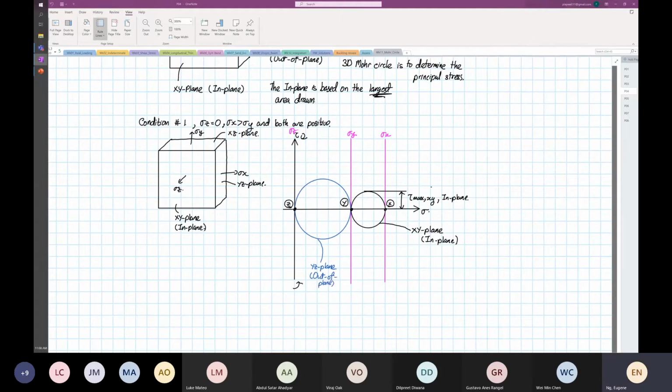And what you realize is now the diameter goes bigger. Okay. And then where do you have that? Over here now, which I'm drawing now. This is your shear max in your YZ plane. Okay. And it's out of plane.